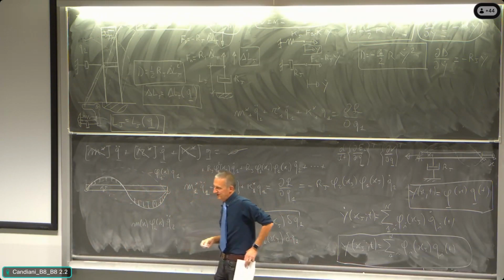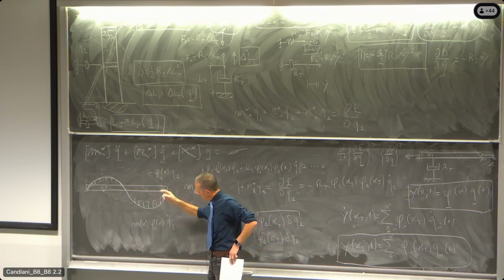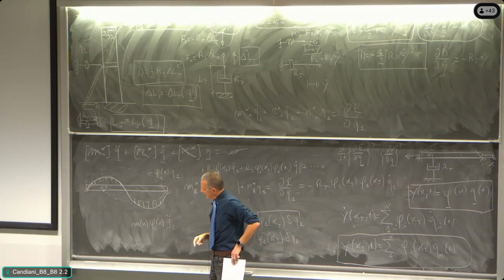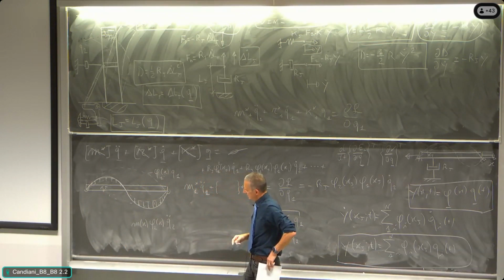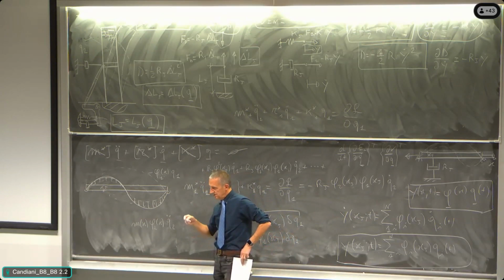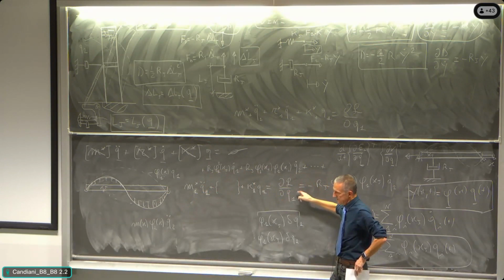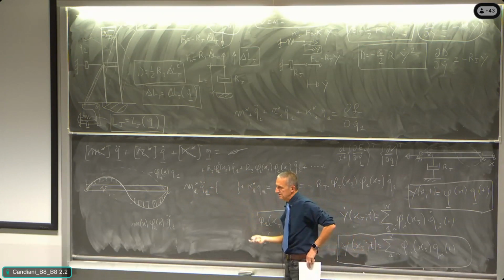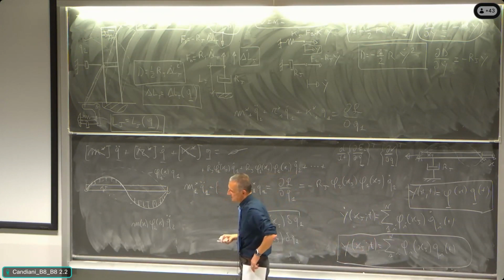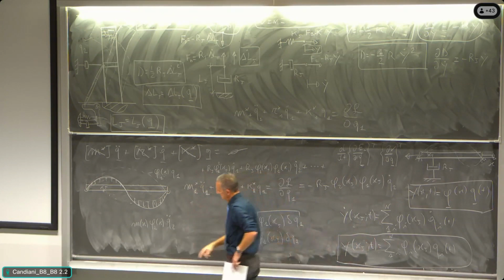So I prefer to explain with a direct example here that, writing the forces associated to the distributed inertial action, and writing the contribution of those distributed inertial actions into the work done by virtual displacement, all the out-of-diagonal terms disappear, and we have just the diagonal term that is the modal mass.